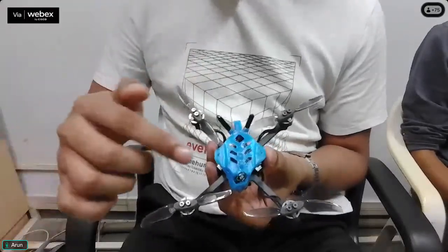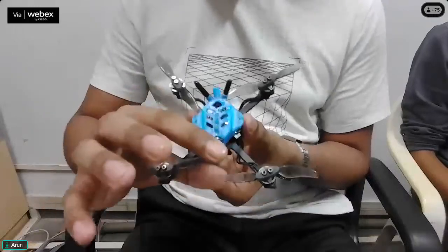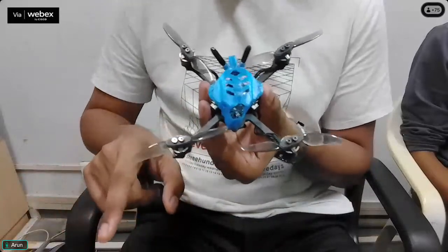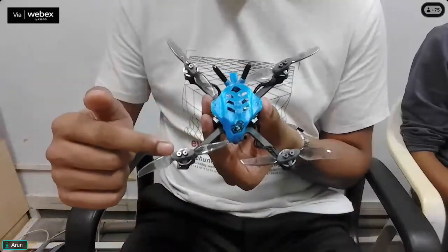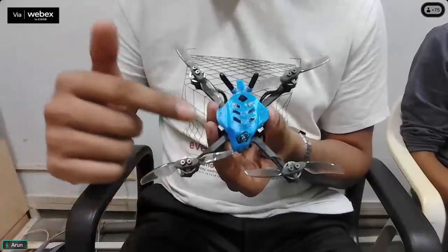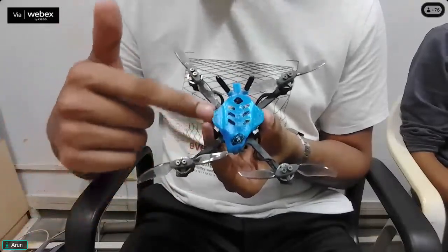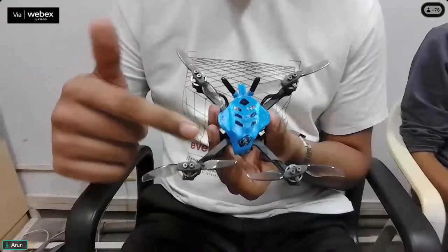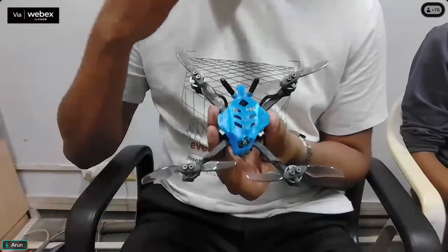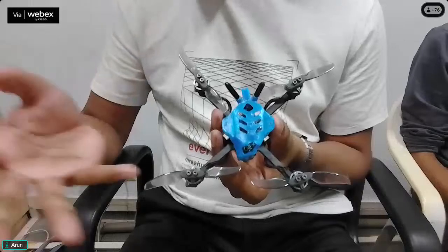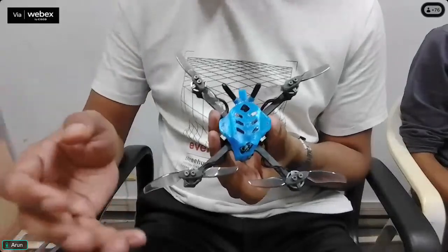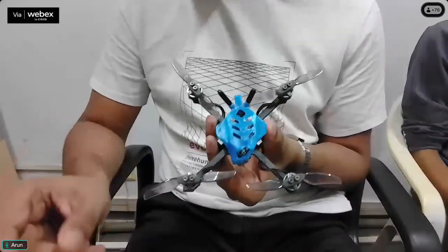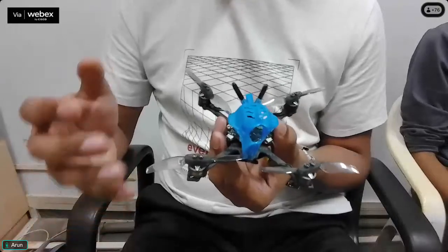And as I was saying, the pitch motion and the movement in the x-axis, the front and back movement, are coupled to each other. So these are not independent movements. The rotational movement, which is the pitching, and the linear motion around the x-axis happen simultaneously. So they are coupled. So that is not an independent degree of freedom as we defined. That's why a quadcopter will only have 4 independent degrees of freedom.